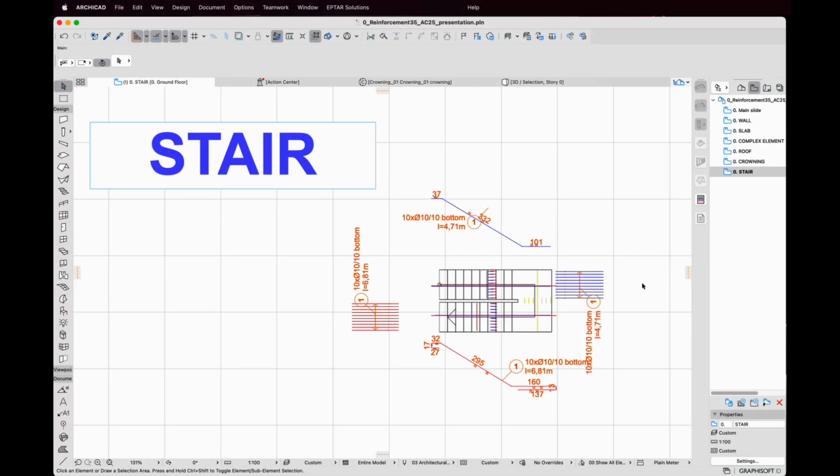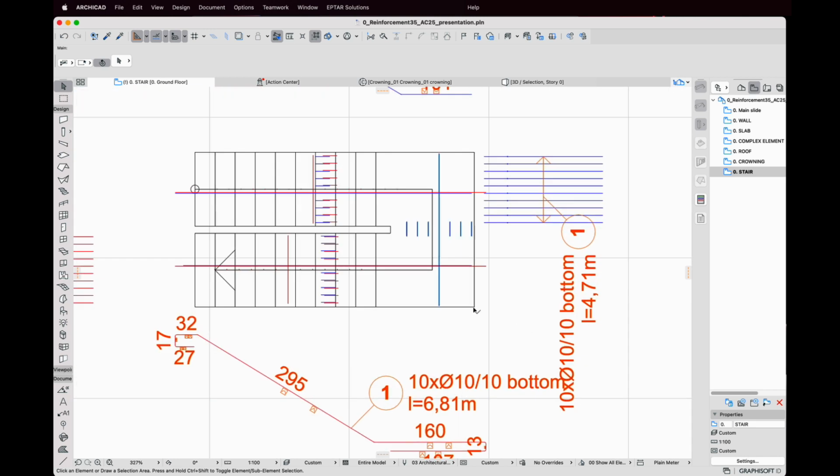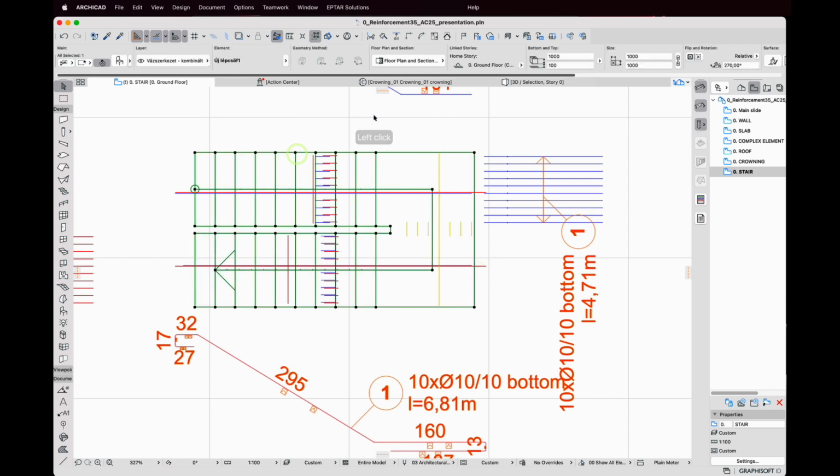Custom shape rebar. Next is the construction when the standard rebar is not enough, and we need to make a special reinforcement. The best sample for this is the stairs, because stairs have a very flexible shape. We cannot place automatically the straight, horizontal or vertical reinforcement. We have to use a polygon rebar for it.